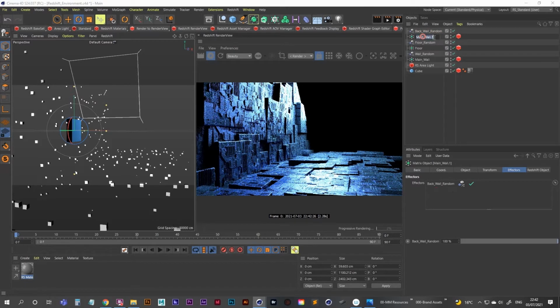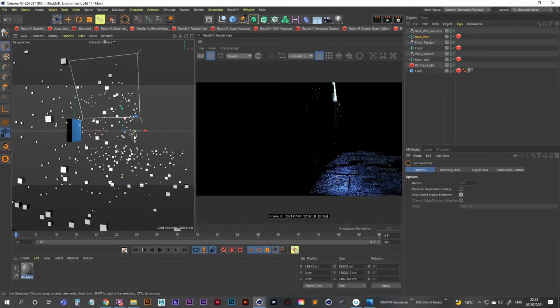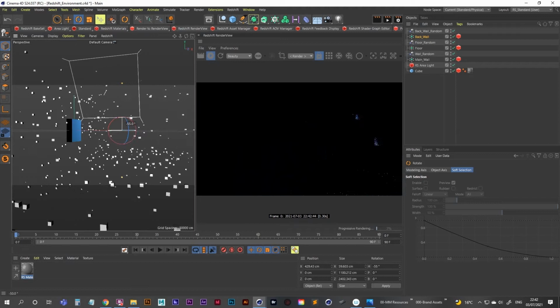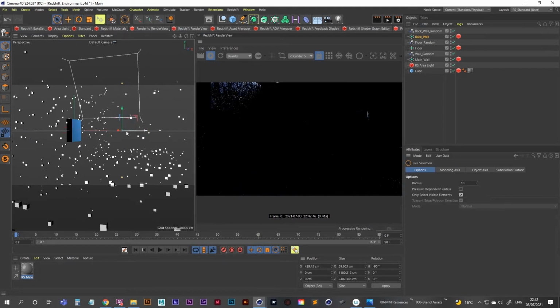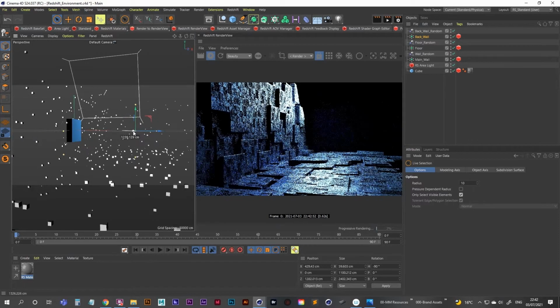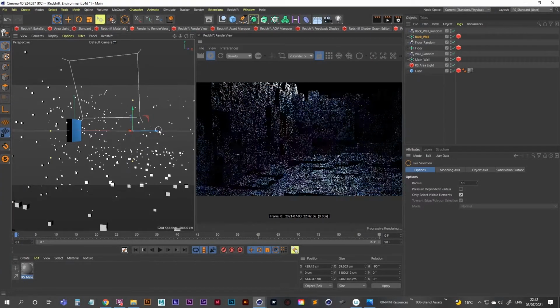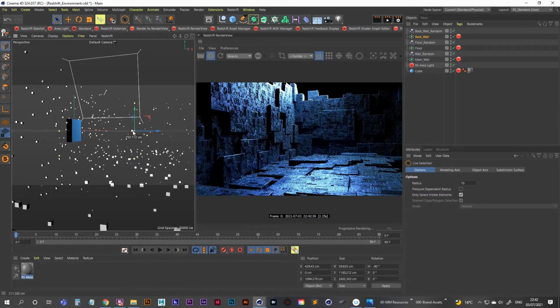So now let's rename this to back wall. And now it'll be easier to set this up. We can drag it over, hit R on our keyboards, and rotate this 90 degrees. Hold down Shift to rotate in increments of 10 degrees, by the way. It just makes it a lot easier. And now we have our back wall. So, get back, you back wall.